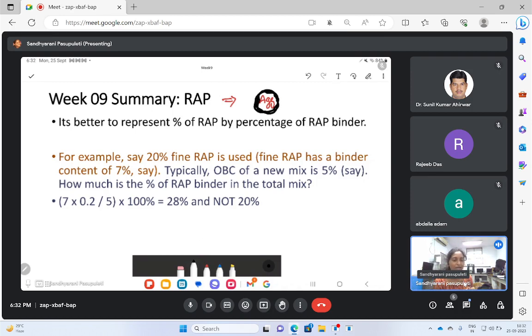So when I collect the already existing pavements, those aggregates are not just aggregates. Let us say this red color is aggregate, there is some coated bitumen. That is the reason why all the tests that we are going to perform on this RAP are not direct. Let us say specific gravity of aggregates. How we perform it on virgin aggregates is completely different from the RAP aggregates, because in the virgin aggregates, aggregate is the only single specimen, but here aggregate has some bitumen coated over that. So how do we actually go forward with this RAP related test?